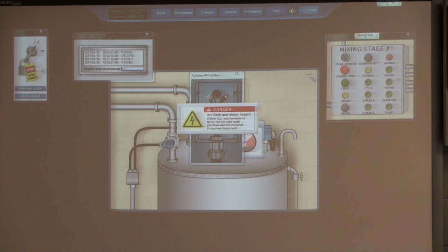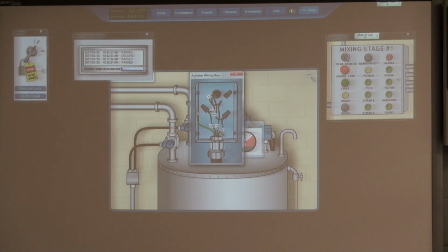Measuring the pump, you can do the same thing here, you can actually take the wire nuts off. Yeah, I was gonna ask you to take the wire. You're gonna need a screwdriver to take the wire nuts off. Oddly enough, my guess is they just didn't wanna incorporate a wide array of tools. Now there have been times that I have, and I'm telling you this only for your own benefit, but if I took a wire nut off of this guy and I wanted to do a live measurement, I would make sure it was not touching the back of the cabinet before I applied power. This thing assumes the same thing, so you can't actually make live measurements with wire nuts off.